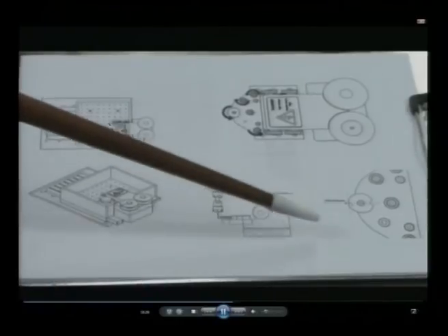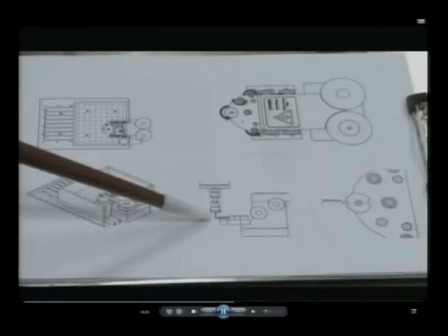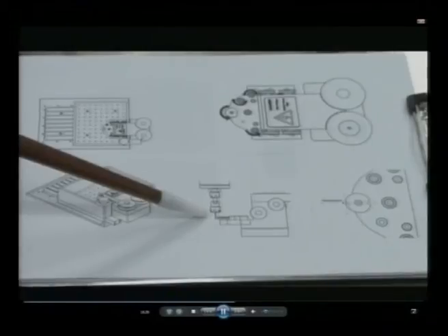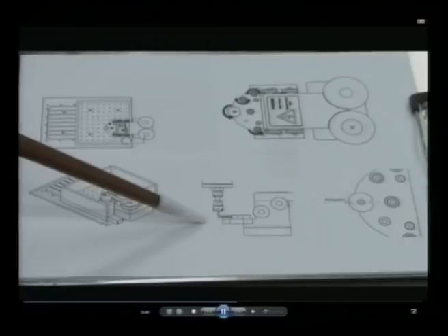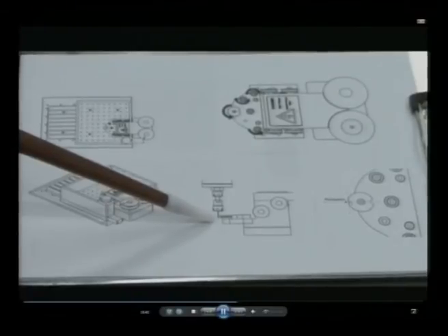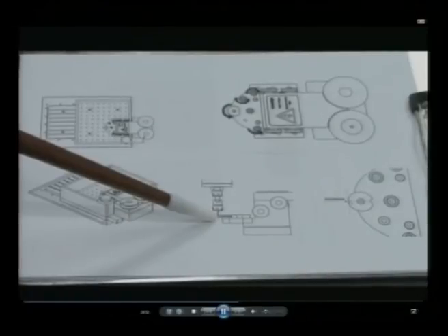The process happens in a way like this. The tool, which is now the workpiece, is fixed on the spindle and rotated. Now the objective of the process is to reduce the diameter of the tool. To reduce the diameter, the tool comes in contact with the wire electrically. Same as the EDM process, the tool material is removed and thus the tool is turned to a specific diameter. Through this process, a tool diameter as small as 2 micrometer can be generated.